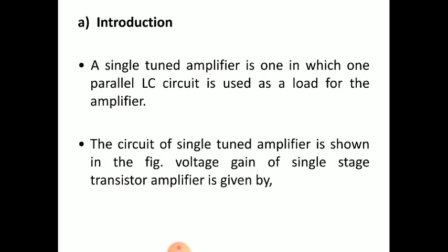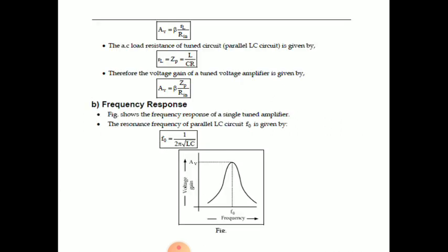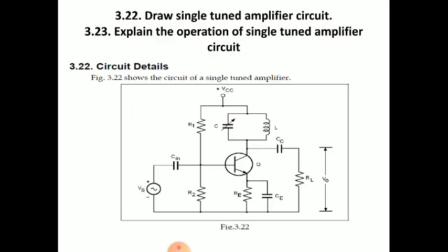The same concept applies here. We replace the resistive load with a tank circuit, that is an inductor with a capacitor, which will act as a tuned circuit. In that case, the frequency response curve is a resonant frequency curve, which we will discuss in the further slides. The circuit of a single tuned amplifier is shown in the figure, and the voltage gain of a single stage transistor amplifier is given by